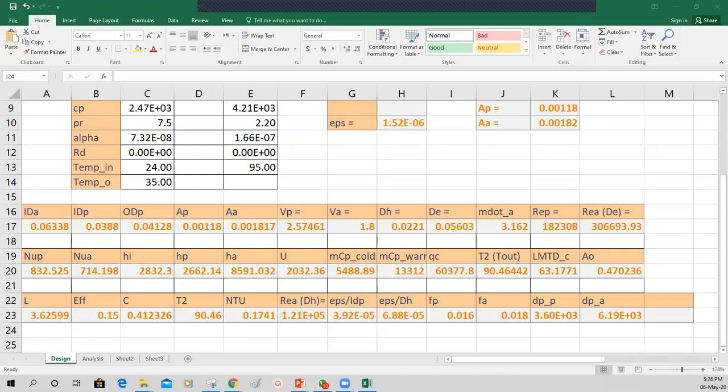All these values, and its unit is watt basically. So how much is this coming? Can you calculate? 90 centimeter cube, so 90 into 10 raised to the power minus 6 is meter cube per second now. And then you multiply by density, so it's kg per second now, multiplied by 4181, and then multiplied by 50. How much is this coming? Calculate.